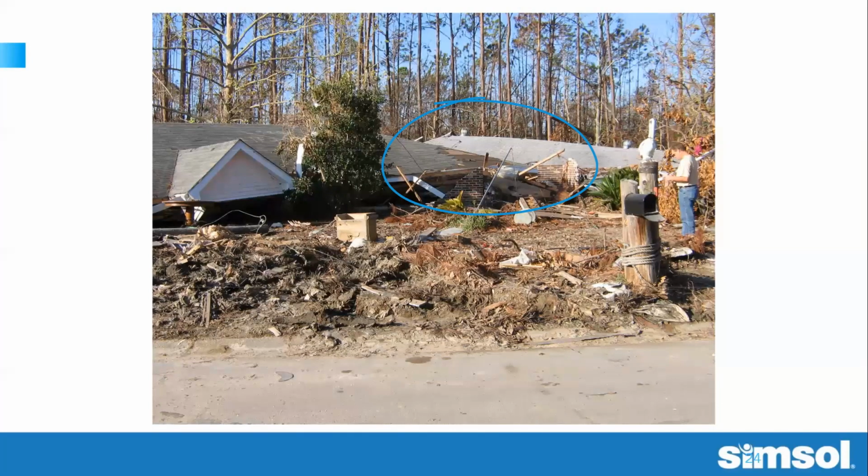I would attest that, given the destruction here and a little inside information that I have on this file, this is primarily a flood event where the building walls collapsed, and the damage to the shingles in that corner is due to subsequent wave run-up after the building collapsed and the surge was still present.